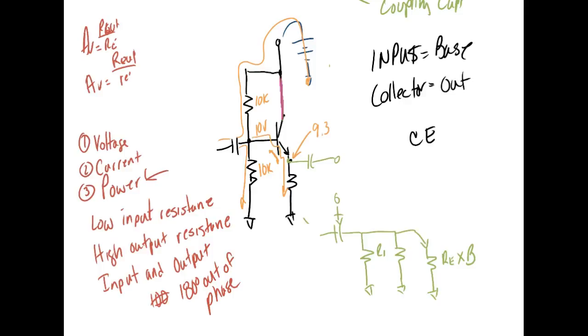So what we find out, this is called a common collector. Number one, the voltage gain would always be close to 1. Now what we're going to do is bias it on. So right now, let's say I'm going to put 10 volts up here, right? You understand. Then we would vary these a little bit.